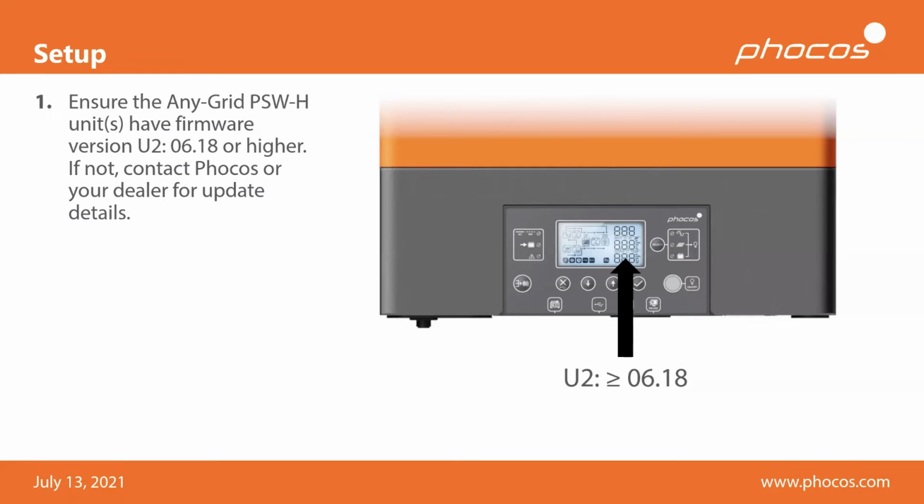The requirement for doing the firmware update is essentially just an RS-232 port. Of course, many computers nowadays don't have a native RS-232 port, so there are RS-232 to USB converters, which will typically cost you between $5 and $10 US. They're available pretty much anywhere on online platforms and in pretty much any computer store. And the cable that's required to do the firmware update is already included with every PSWH. Once you do get the update files, regardless of whether you get them from our website or from our support team, there are detailed instructions with screenshots on how to do that.